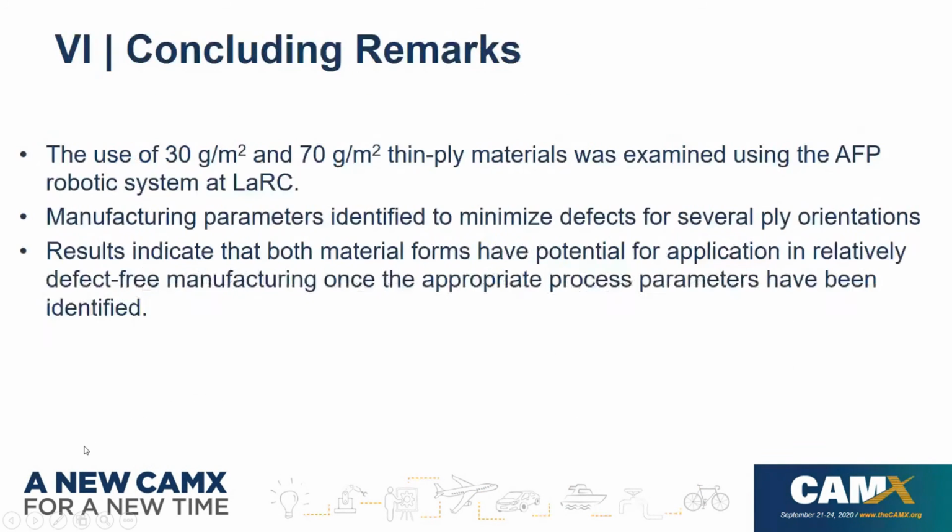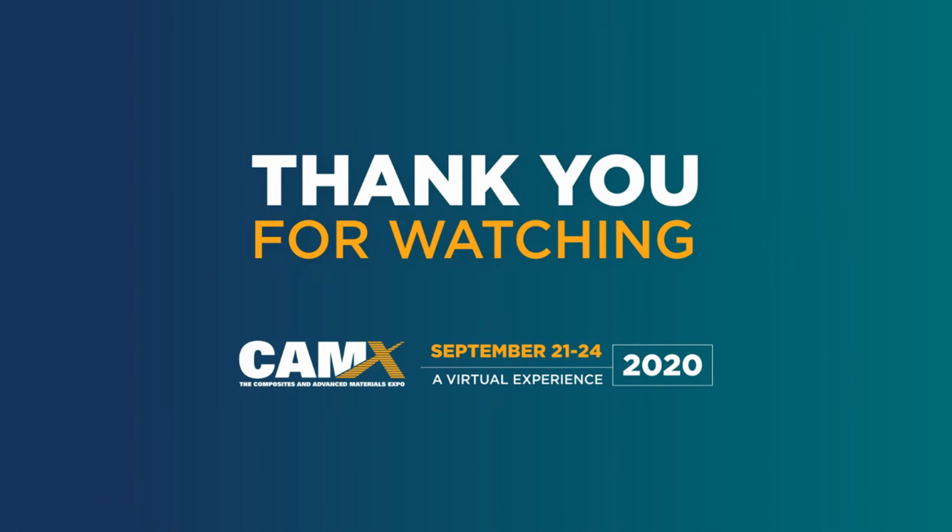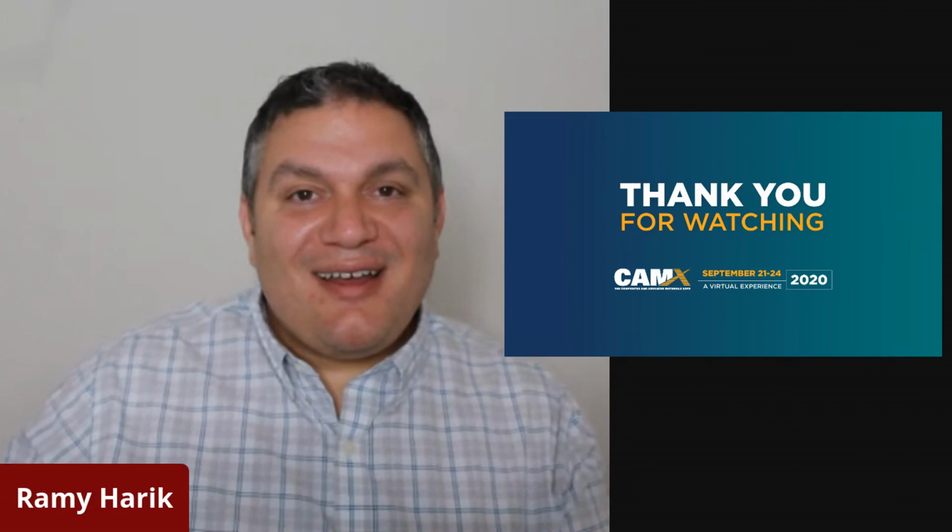And finally, to conclude the remarks, the use of the 30 GSM and 70 GSM was examined using the automated fiber placement robotic system at Langley. We identified the manufacturing parameters to minimize defects for several ply orientations, and the results indicate that both materials have potential for application in a relatively defect-free manufacturing, obviously while using the optimal manufacturing conditions.